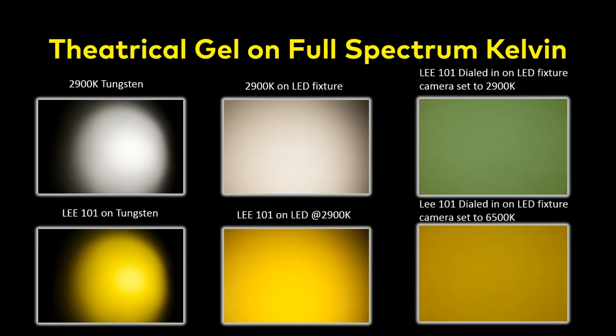At 6500, it came in desaturated just as I would expect. So what it shows me is that the spectral response of that chip at 6500, which is its native Kelvin, pretty much got what I expected. But when you take that, and again, this is all mathematics and algorithms, you turn that sensitivity to 2900, it may fall apart. And I say may because I didn't test all the cameras that are out there. This is just an illustration between a high-grade and a lower-grade camera, and very much the same results.